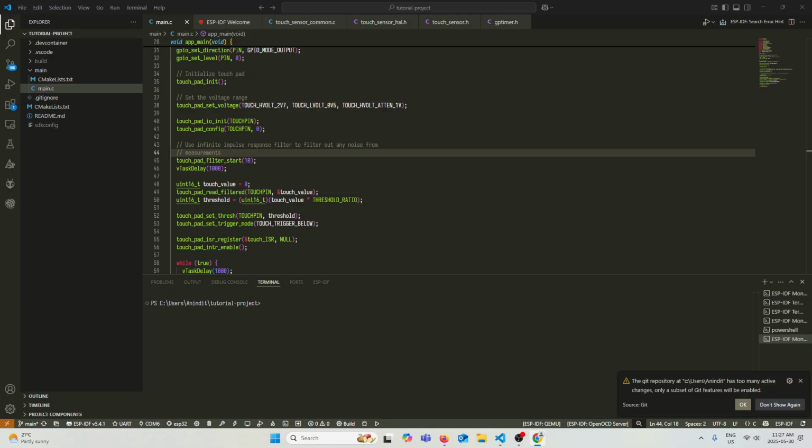The next part of this video will be a brief walkthrough of the API. Note that we are using one-shot mode in this video. We first include the necessary header files, then we create a handle where we have to specify the ID, which is either ADC1 or ADC2, and whether we use ULP, the ultra-low power coprocessor, in our project. You can also adjust the clock source, but normally we just use the default one. Then we create a channel configuration with its bit width and attenuation value. We call ADC one-shot config channel to apply it on a specified channel. Note that you can apply the same config with the same handle to multiple pins or channels.